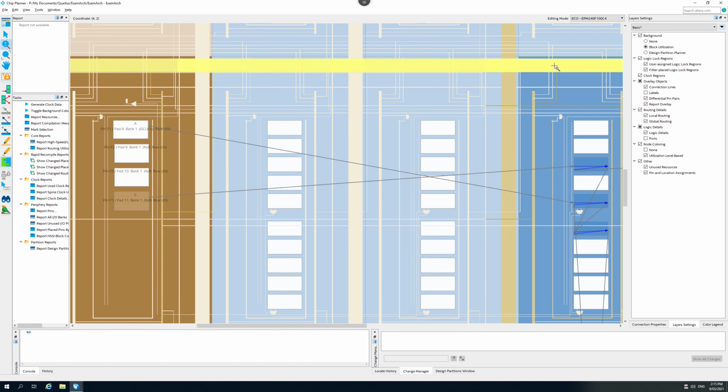At every junction there's a switch. FETs are just electronic switches, so what happens when you configure the FPGA is that you store into memory what each switch should be. Should it be open or closed? And the memory just gets sent out to each of the FETs to actually do the opening or closing, to work out whether there is a connection between intersecting wires or not.